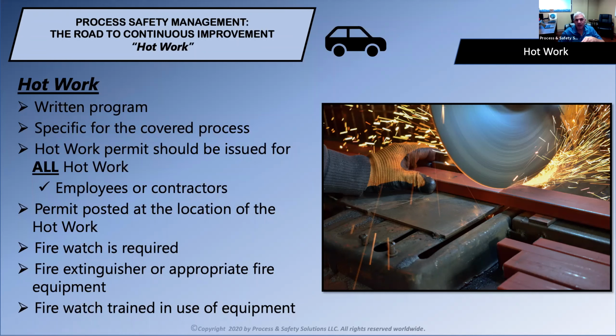A Firewatch is required, so there's no exceptions. If it's hot work, a Firewatch is required. A fire extinguisher and appropriate fire equipment must be provided in the immediate area, and the Firewatch must be trained in the use of that specific equipment.